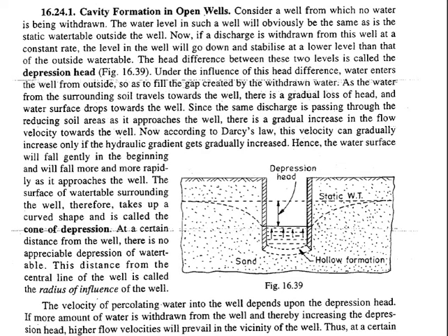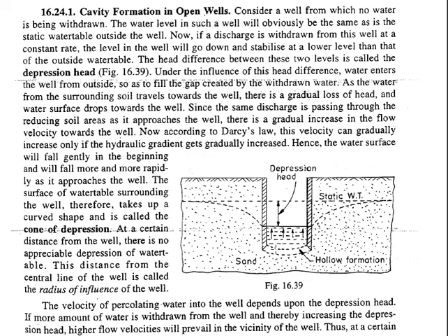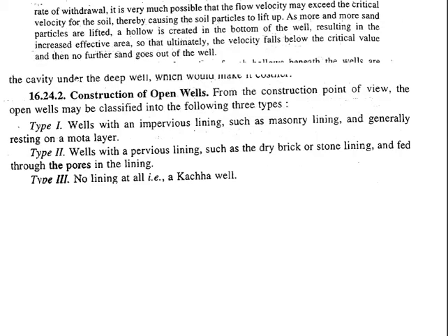And when the velocity of the water is high, it is more possible that the flow velocity may exceed the critical velocity of the water, and when this happens, the soil particles are lifted up, and a cavity formation will take place. But as the process continues, the velocity decreases and this process stops. But for that period of time, we have a cavity or hollow formation. That process is the cavity formation.